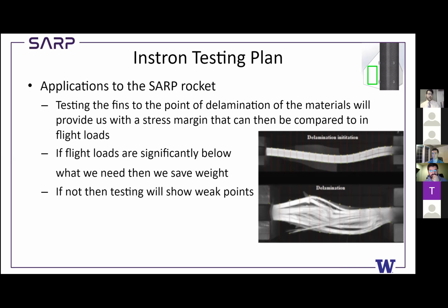So what happens is if you were just to go through a normal turbulent flow, your fins would vibrate, but as long as you've designed them, they shouldn't come apart. However, at particular speeds, you'll introduce harmonic motion, which will increase all of the pressures that that fin experiences, which often leads to failure. It's well documented on several sounding rockets from different organizations.